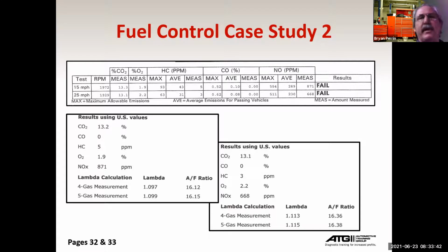Plus, this was a real pain to check fuel pressure on, so I didn't want to do it, right? A lot of times our tests are based on what's easy to do. This was hard to do. And so I can do the test blindly, or I can apply logic and exclude it. In this case, I applied logic. The thing runs great going down the road. It ain't a fuel pump problem. It ain't a plugged filter. So I really proved in my mind it couldn't be that, without any testing other than I drove it and it drove great. People kind of laugh when I go, well, how's the car run? Well, what does that have to do with it? I'm trying to fix the code. What kind of sets us for what could or couldn't be wrong?